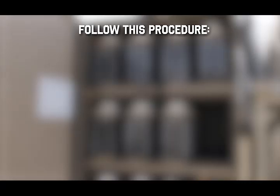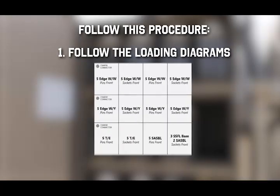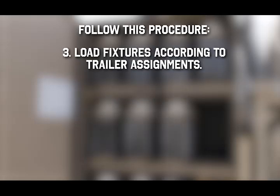Follow this procedure. First, follow the loading diagrams inside each rack door. Start electrical connections from the rightmost column working left. The pattern is simple. Column 1, pins front. Column 2, sockets front. Column 3, pins front. Column 4, sockets front. Load fixtures according to trailer assignments.